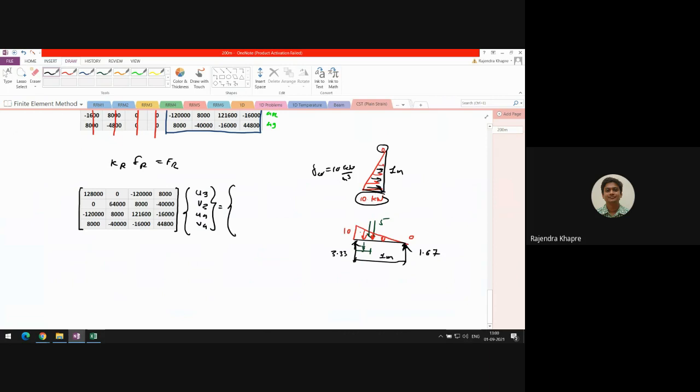I am just drawing the rotated view of this. I have drawn a simply supported beam which is 1 meter in length, because the height of the wall is also 1 meter, and I am going for the triangular loading on that simply supported beam. I am calculating the reaction of that simply supported beam when it is subjected to a triangular load, where the value of load continuously reduces from 10 to 0.